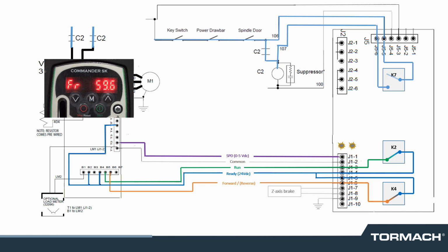Our diagnostic processes walk you through observing the VFD display for these conditions and instruct you on procedures to resolve issues that you may encounter. As a final review, I'll remove the signals and show the VFD displays you would encounter during troubleshooting. Removing forward reverse, the spindle rotates in reverse regardless of the setting in PathPilot.